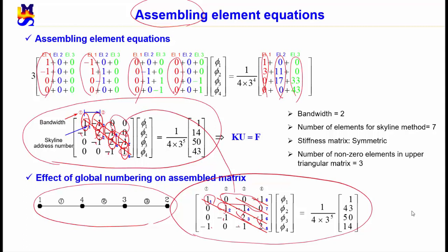Node numbering has an effect not on the final solutions but on the position of stiffness matrix elements and force vector components, which may affect computational time depending on the scheme of solving a set of linear equations. Therefore, optimal node numbering scheme depending on linear equation solver is employed by most software, indicating that just users of finite element software don't have to think much about detailed finite element techniques, which can be carried out automatically by the software, especially when a functional automatic finite element mesh generation technique is employed.